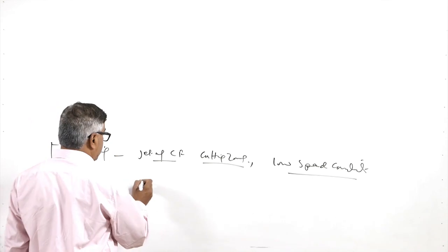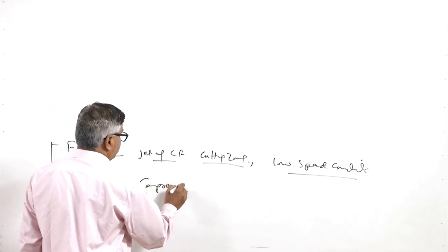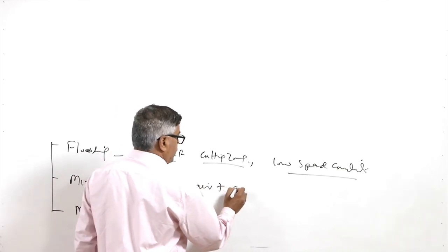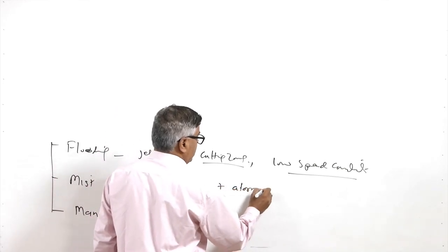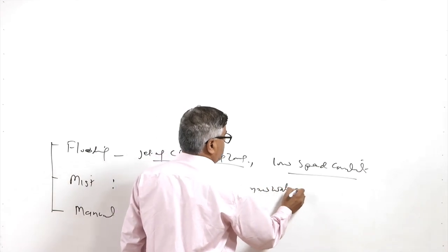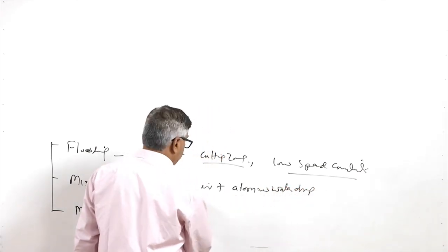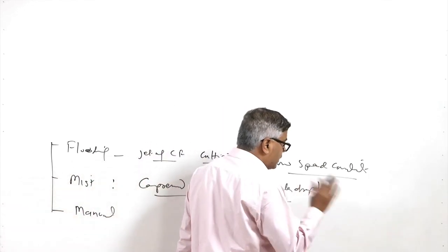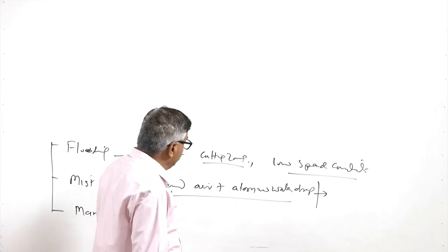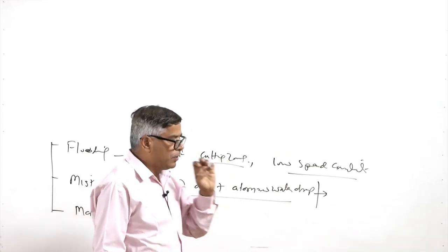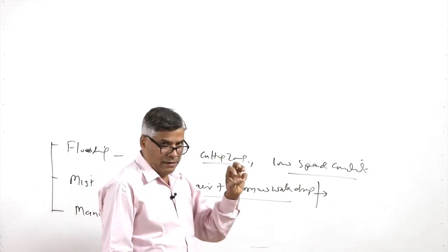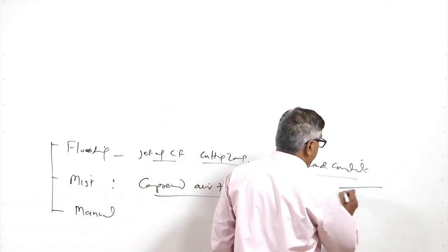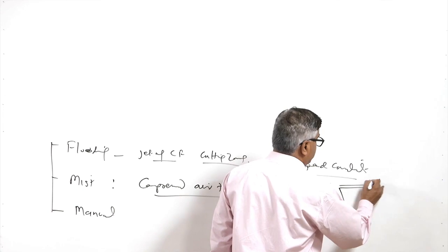On the other hand, compressed air plus atomized water drops, the combination of these two called mist, is directed into the cutting zone. Since the mist will be fed under pressure, at high speed conditions this may be able to reach the tool chip interface during the machining.